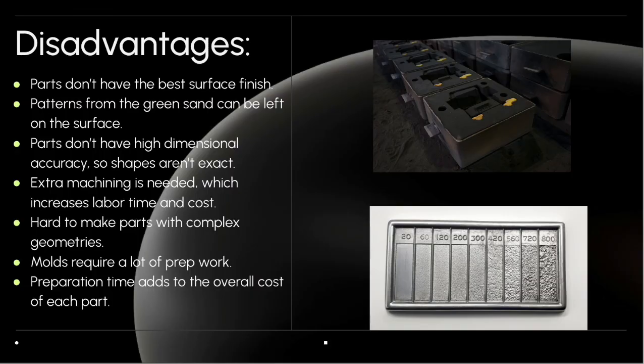It's also difficult to use sand casting to create parts with complex geometries. Another drawback is that the mold requires a lot of prep work. The preparation time needed to create each mold can be long and also adds to the cost of each part.